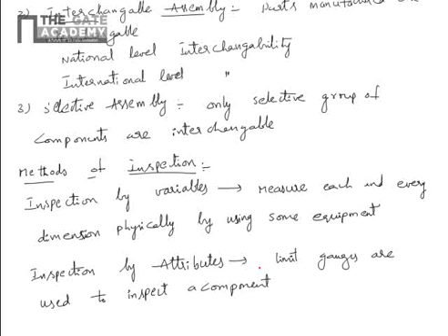The gauge is also of two types, go gauge and no go gauge. The shaft has to enter the go gauge, and it must not enter the no go gauge, then that component is accepted. So gauges are used to inspect the component.